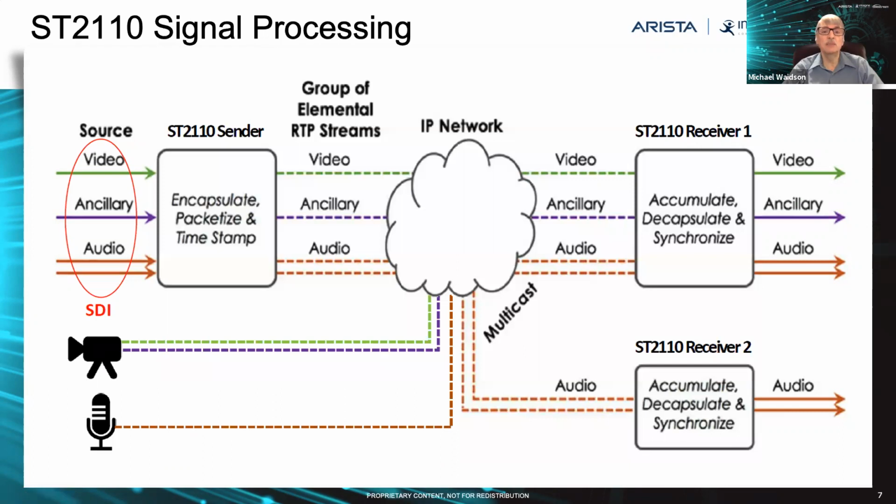So here in our system, within 2110, the video, audio, and data streams are carried as separate flows across the network. This allows for flexibility in manipulating the video, audio, and data signals in a live production workflow. This is similar to SDI in the workflow, carrying audio separately or embedding it within the SDI along with your ANC data. So you can choose to encapsulate the SDI signal with that embedded audio and the ANC data and carry that in SMPTE 2022-6 for transmission across a network.